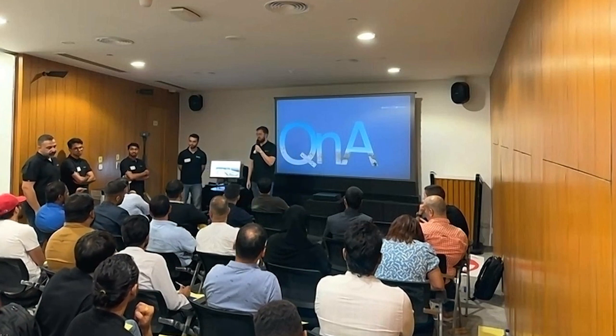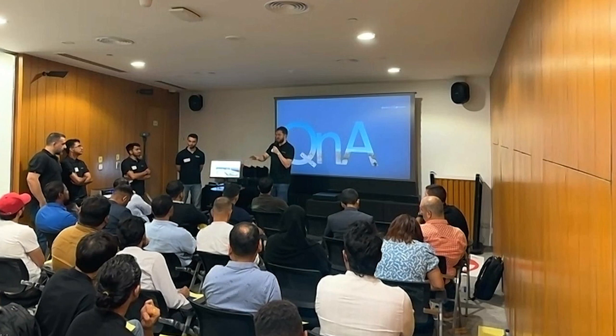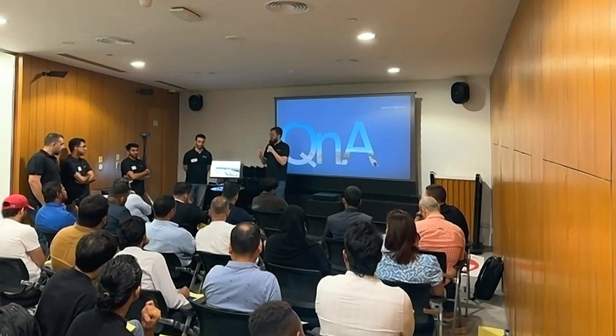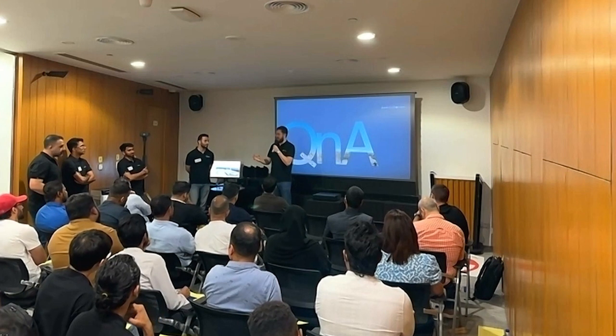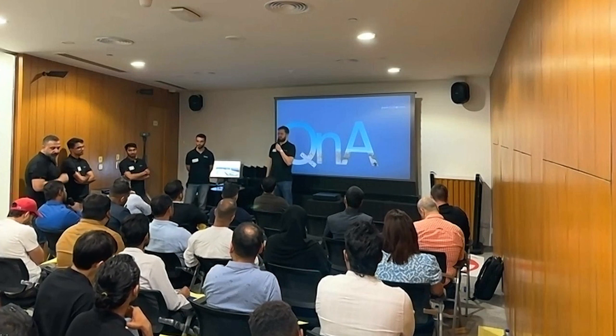Again, same question: is PPK available or not? No, this is RTK only. When we talk about PPK, it's about post-processing of that RTK data. Exactly. So in terms of PPK as a module, no. There are other platforms out there that offer a PPK module, but because the RTK is so accurate, it's not really a major undertaking. How we improve our accuracy if we're not happy with the RTK is to post-process that RTK data. That's the difference. Hope that answers your question.